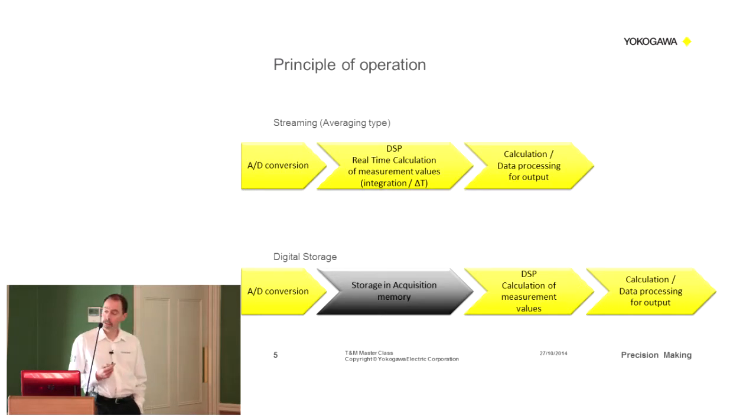So essentially, that's the drawback of using an oscilloscope-type product, a waveform analysis type product, for measuring power, because there are bits you miss. If you are looking to integrate power and look at your watt hours, you won't be measuring all the watt hours because there are dead times associated with it.